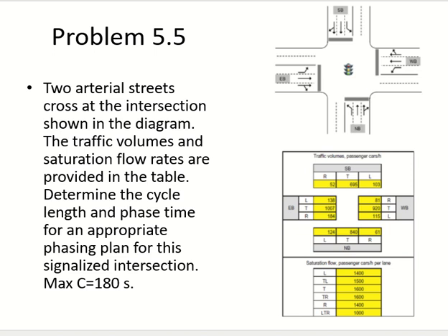The first thing is we decide about the left turnings. The left turning should be protected or permitted. If they had given us the speed of any road, any road having a speed of 45 miles per hour or higher, we would say that it is protected. But in this case, speed is not mentioned, so I cannot use that criterion. I'll use the numbers then.